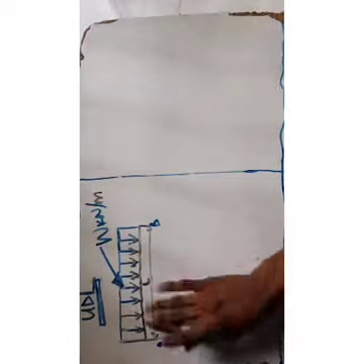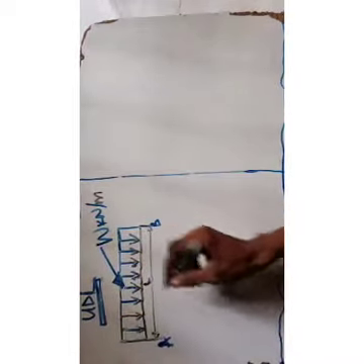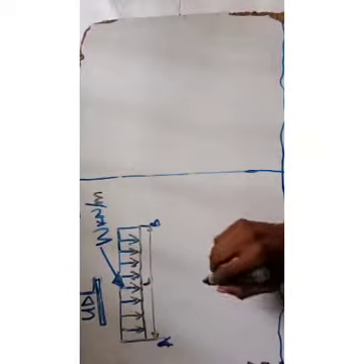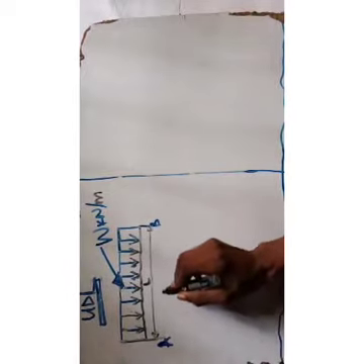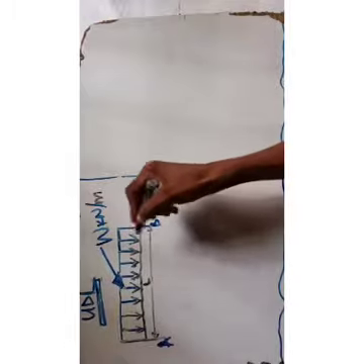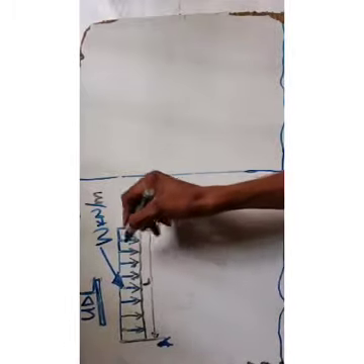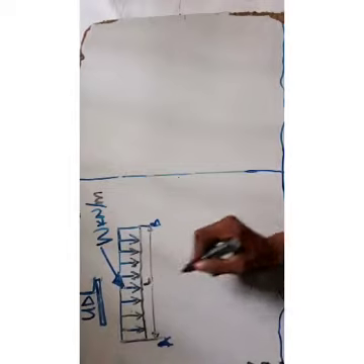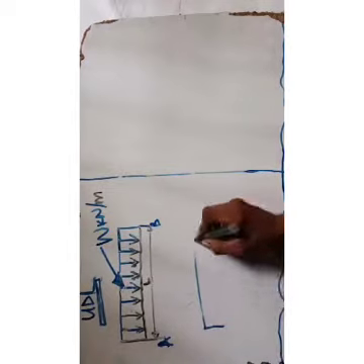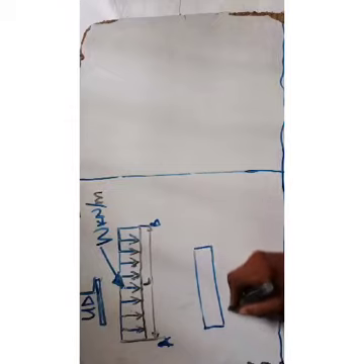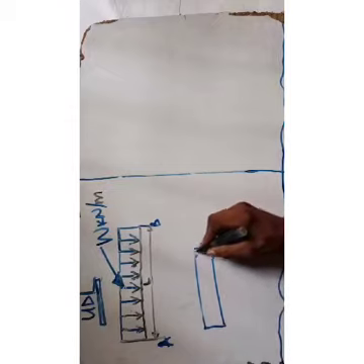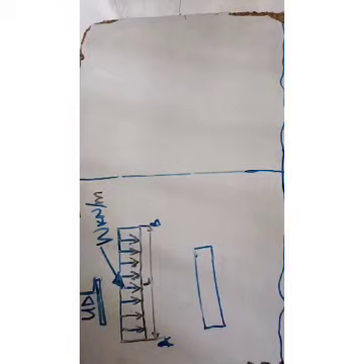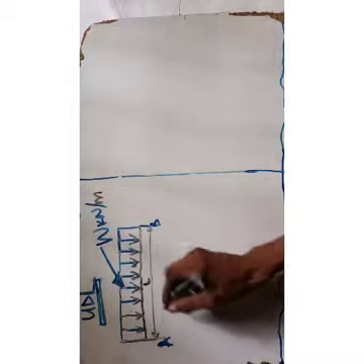Okay, so UDL, uniform distributed load, and for example, like this is uniform distributed load. It distributes accordingly and it varies equally. So here is length L. If you don't forget from the previous examples, this is point load and this is in form of a rectangle. So for UDL, to calculate, you would need to convert UDL to point load.